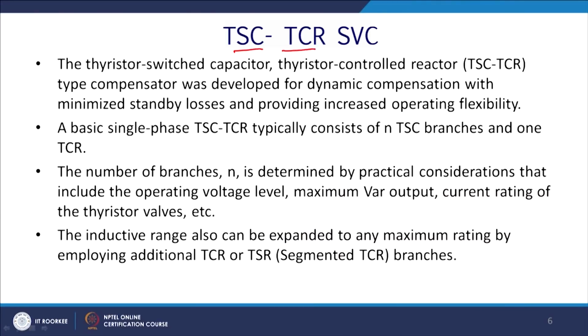You may put it on and off by mechanical switches. Now, you may have a TSC-TCR combination. Then you will also have a thyristor switch, so it can manipulate turn on and turn off, as well as you have the TCR. So, the thyristor switched capacitor and thyristor controlled reactor are the types of combinations.